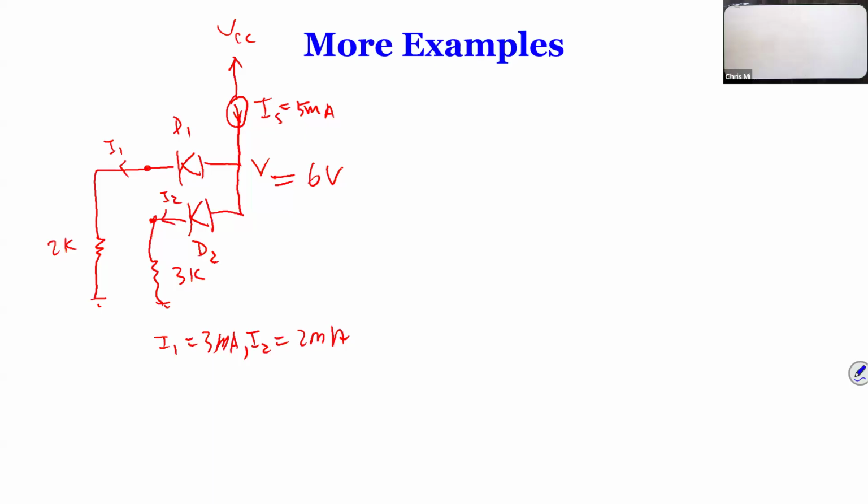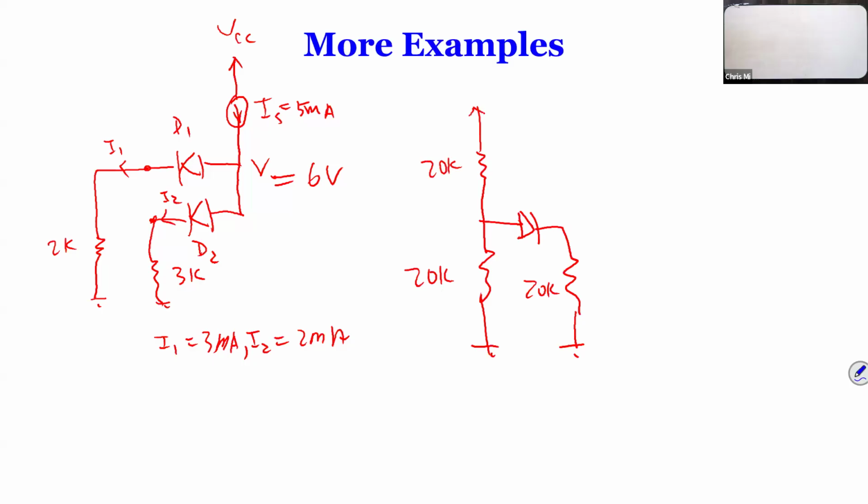Now also, like in the book, for example, problem 4.8 has a circuit like this. So in this case, if you look at the circuit, can you say this diode is on or off? It has to be on, because if it's not on, immediately you see 2 resistors in series, you got 5 volts, so you get 2.5 volts, and you got 0 here, which is no good. So it has to be on.